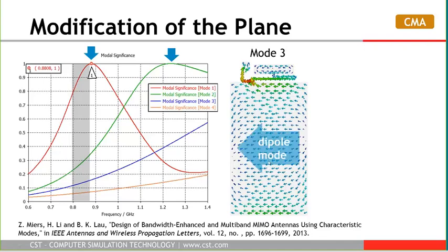And if you look closely at the current at the ground plane, you can see that it's a current of a dipole, a dipole which is very fat and very short. So we know that we can change the resonant frequency of a dipole if we make it longer, but in this case we cannot make it longer, we have limited space.